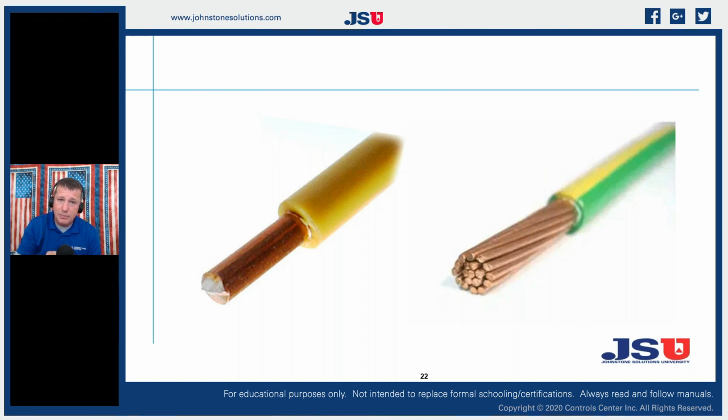So now it becomes important to make sure that our ground wire is even clean and free of debris. Because if you think about that in legacy mode, a ground wire was typically just that, an emergency escape for current to get to ground. It wasn't used for daily communication. Our high voltage wires going to the outdoor unit, that's all we used was the high voltage wires.